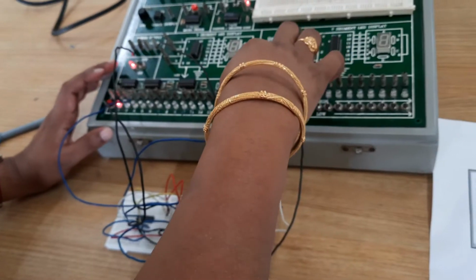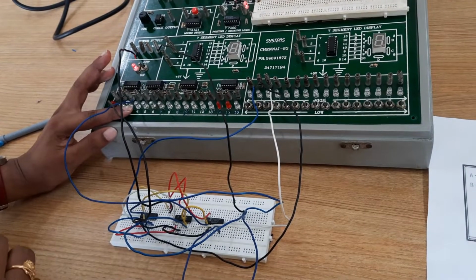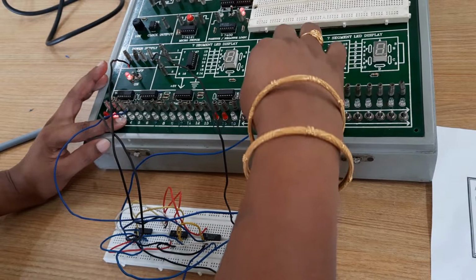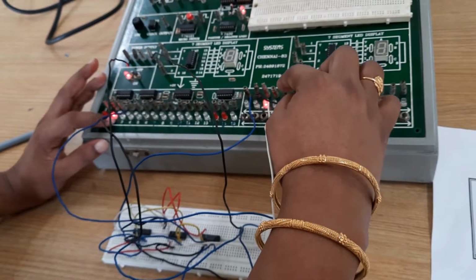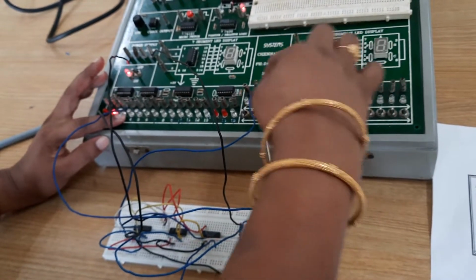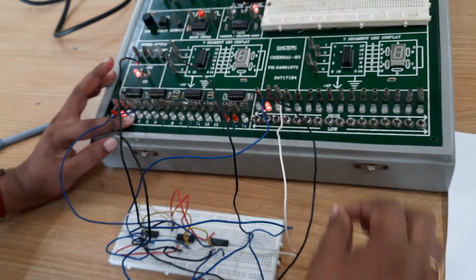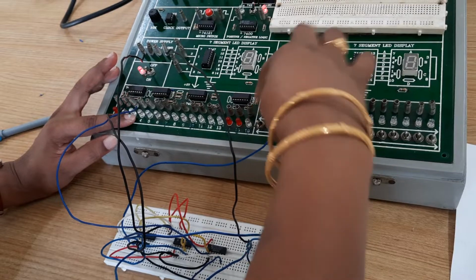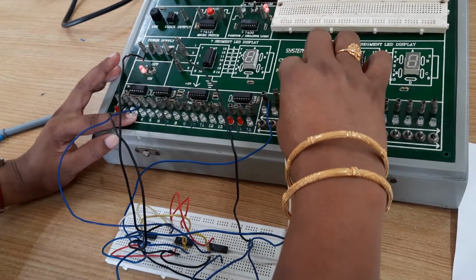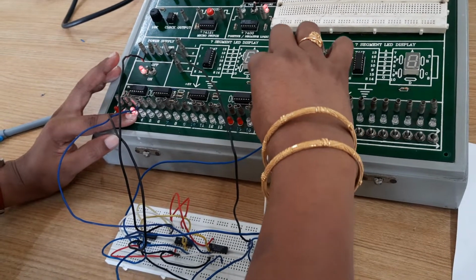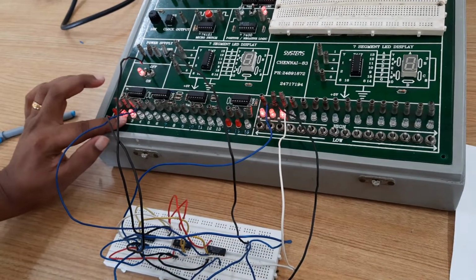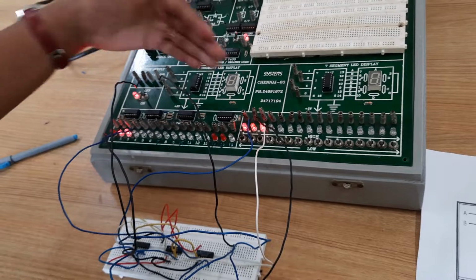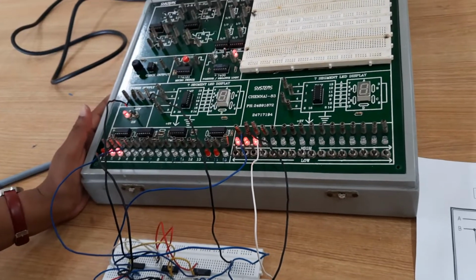Look at this, when all inputs are 0, my output is 0, 0. When I have one of my inputs high, my sum is high and carry is low. Similarly for the other cases. Just to check, when all inputs are high, both my sum and carry out are high. I have checked a few cases. Similarly, you can verify your truth table.